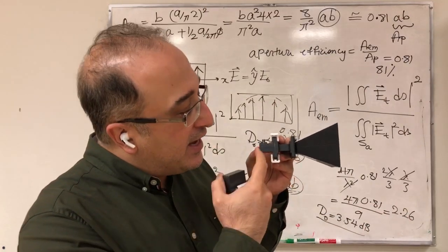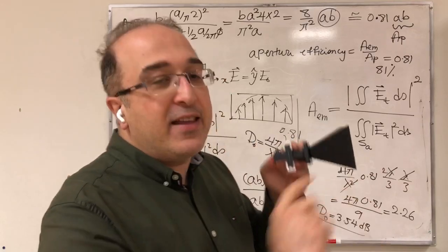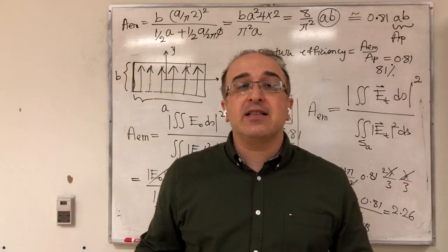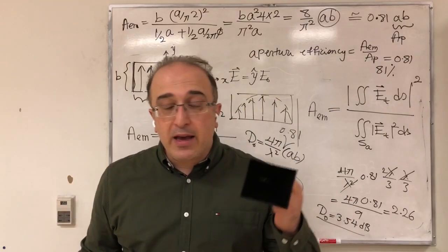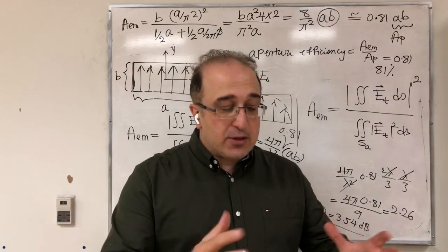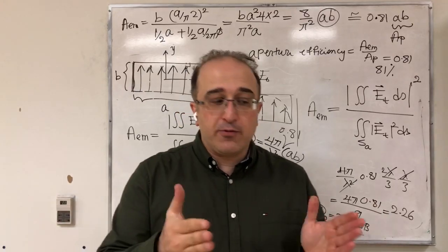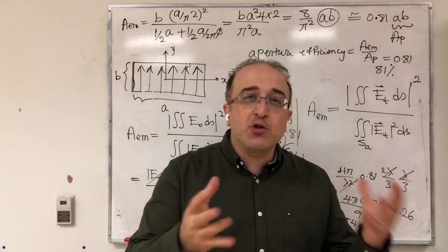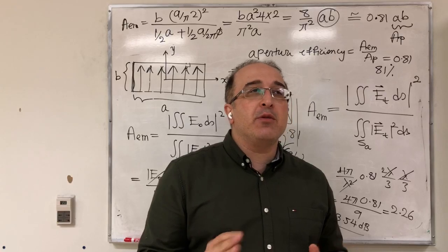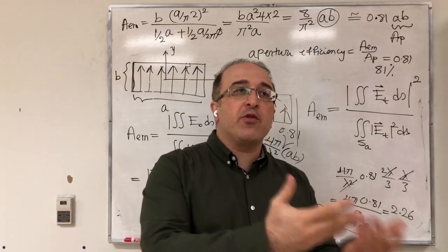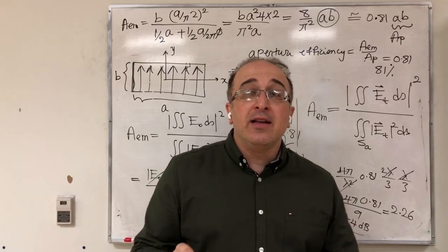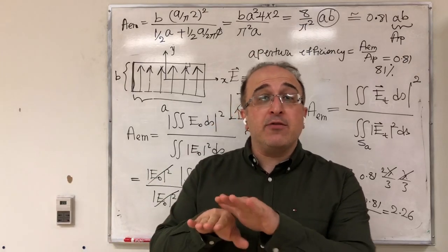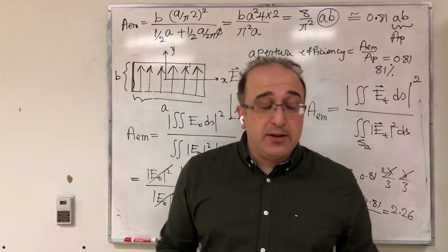Compare this, which is the early part of this structure, and then flaring out, and that's essentially how we make our horn antenna. So we learned that this horn antenna is a transition from waveguide. Think about so many things that we learned. For example, patch antenna evolves from microstrip transmission line. Now horn antenna is essentially evolving from a waveguide into a horn antenna.